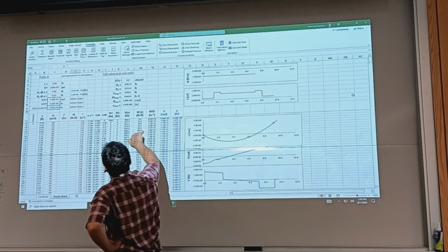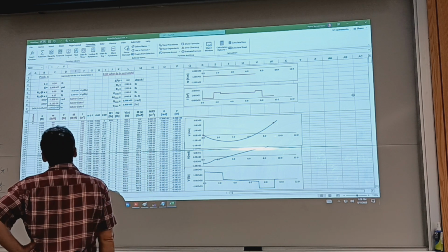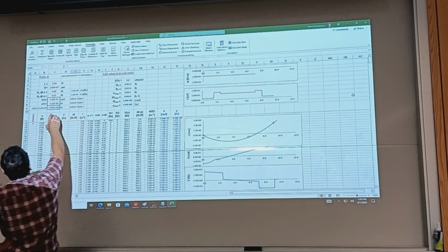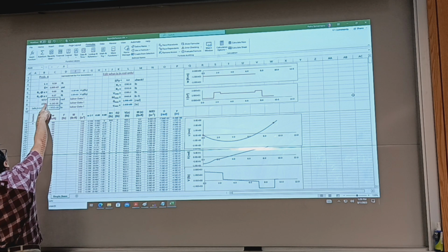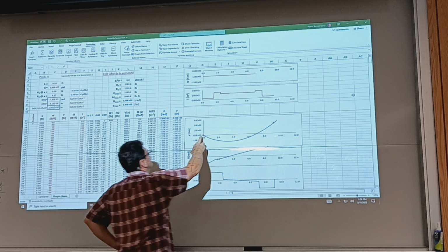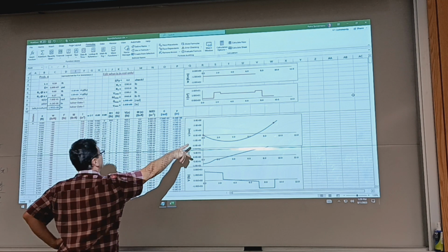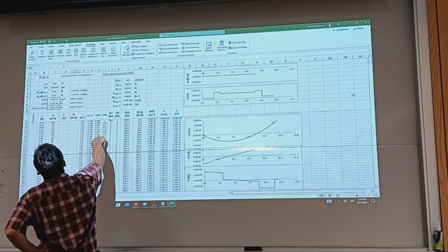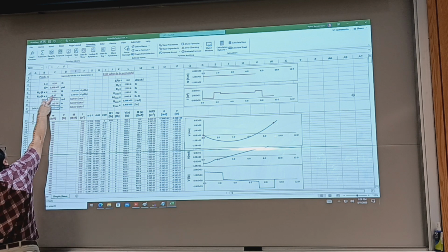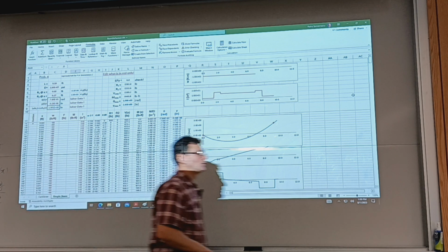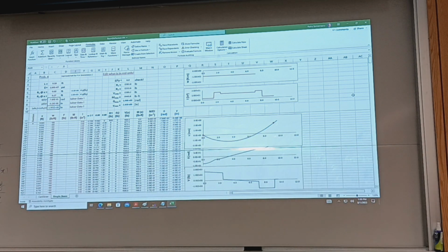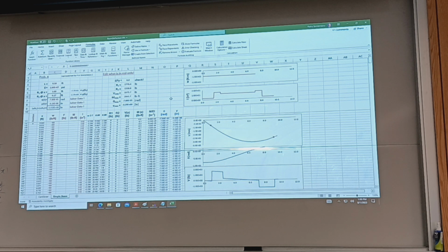So let's see, it says solver data. I have slope at the initial y, or at the support. I can change the support. It says, where is R1? It's at 0. I can change it to where the support does not coincide with the end of the beam. So full length is 9.58 feet, I can make the support at 1 foot inside.